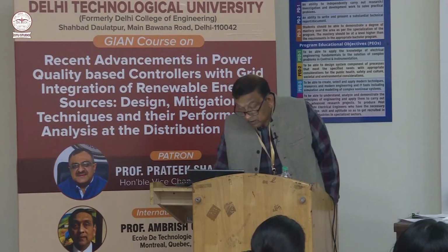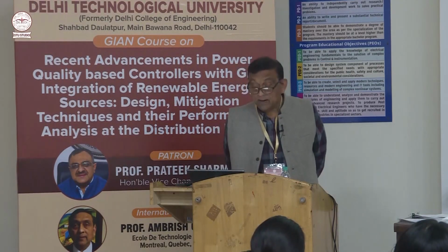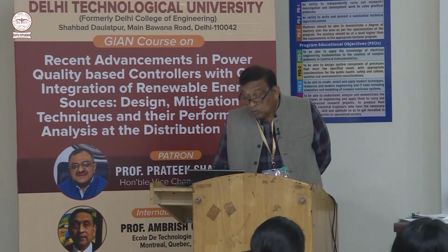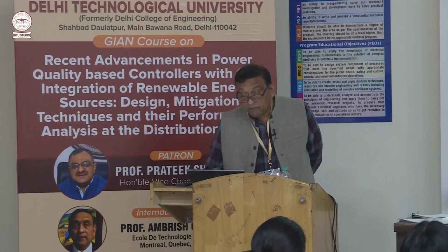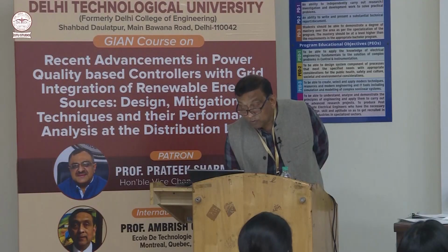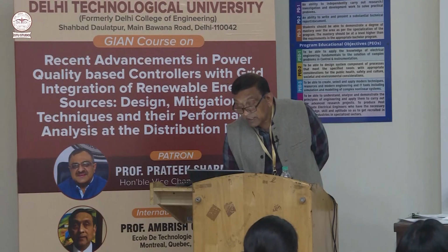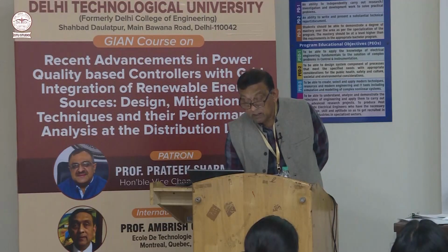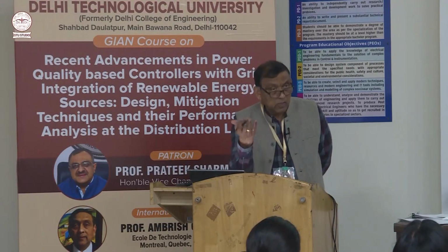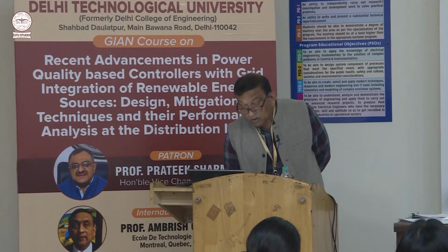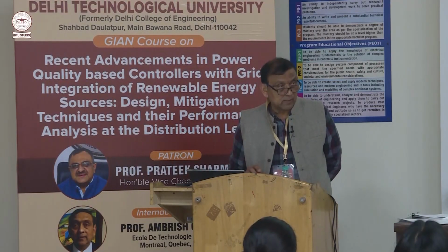These are known as rectifiers, fed by three-phase source. So if you are having rectifiers, there are some power quality problems. On AC side, voltage and current harmonics are generated, poor power factor. We already have the idea of rectifiers, right? And on DC side, you have the voltage ripples.